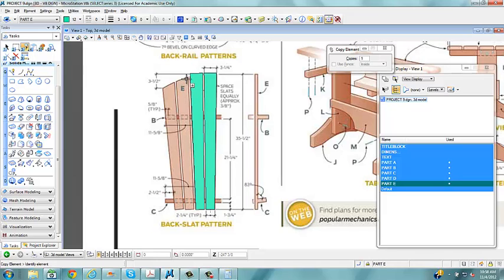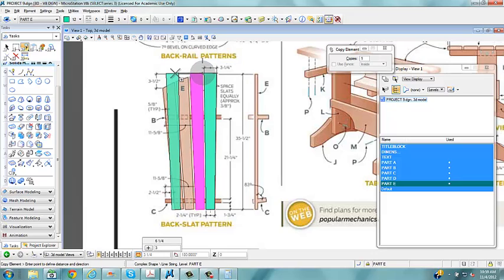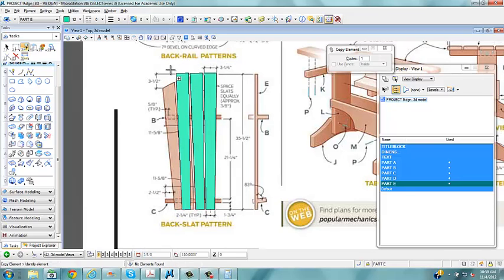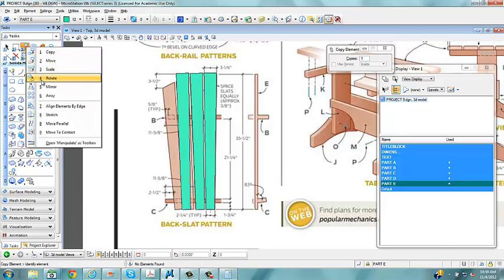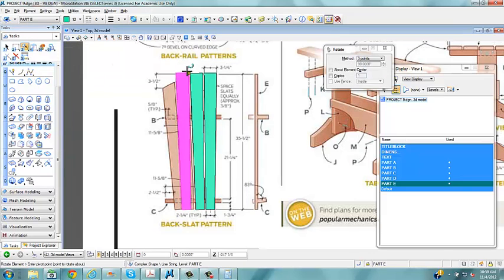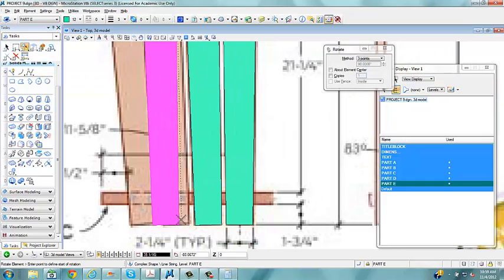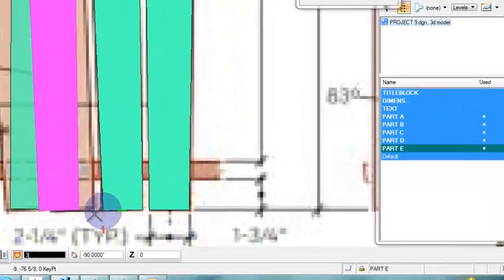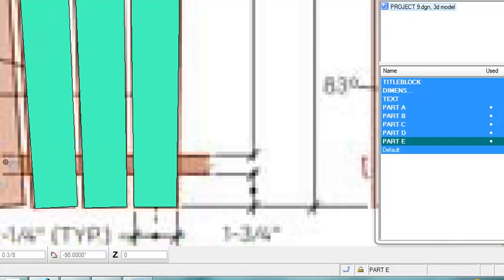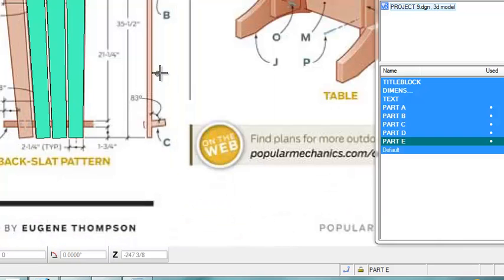We're going to do the same thing. So we want an even line, 3/8 of an inch. So I'm just going to copy this one again. 3.25 plus 3/8. Do a rotate, 3 points, object, corner to this corner, bring it over here, O, go back, 3/8. Getting there.